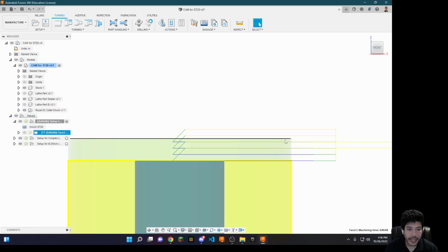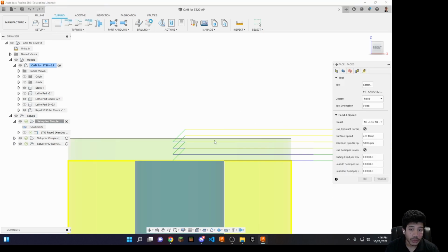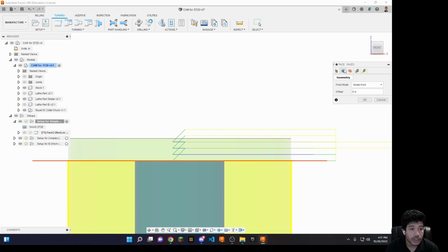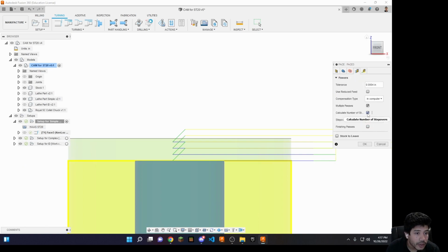And we can do the same thing up here as well, or at least attempt to. Here it assumes that the stock definitely starts here, but if I made any issues with placement of the stock in the chuck, it could start cutting earlier than anticipated. So I go to multiple.